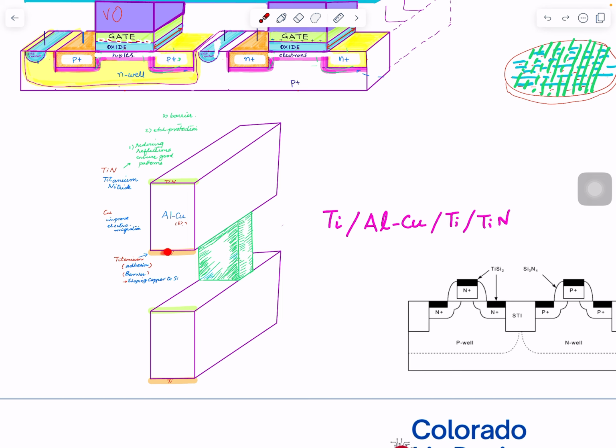On the bottom side of each metal, titanium is used, also for a good barrier and good adhesion. Remember that one. In this case, we use this black thing here, titanium, and titanium nitride, silicide. Anyway, for those, some of the adhesion, a nice barrier into another metal, and ensuring that copper, for example, if it's connected on top of a via here, doesn't go into the silicon and damage it.